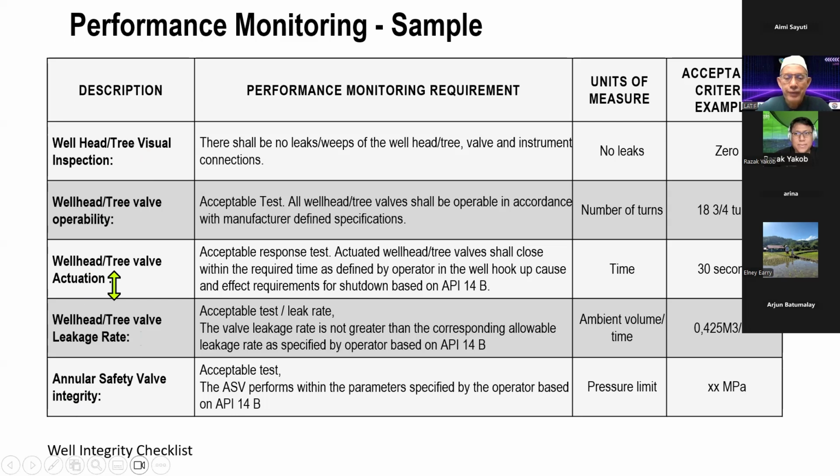Activation, how to activate. If it is air driven or hydraulic driven, there will also be an understanding about how the activation works. For example, some of the activation might be within 30 seconds. So you have the hydraulic valve, and you test it according to the spec. It should be closing within 20 minutes. Then you record. If it's 30 minutes, it's a failure. So they have to do some repair job. So there will be another work scope, that is repair work, if it is not achieving the acceptable closing time and so on, or pressure.